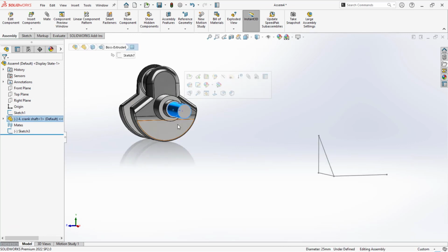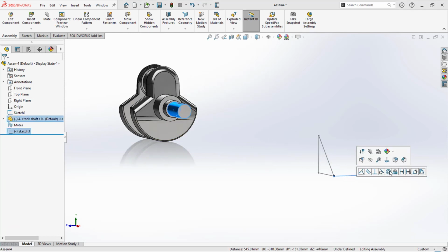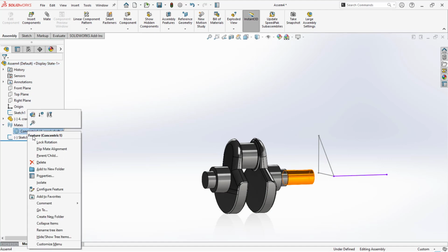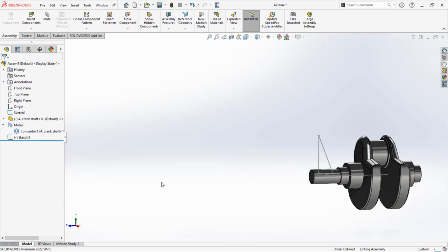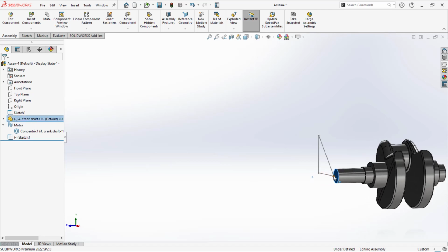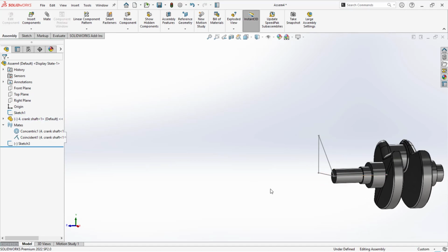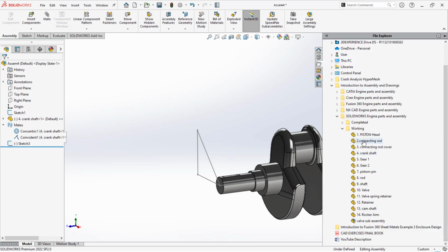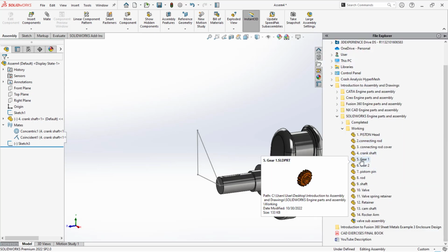So this circular face and this one concentric, I need to flip this. The alignment is something different here. So what you can do is use the mates drop down, right click on it instead of going to edit and making the changes. Just use this flip alignment. These two faces coincident will place it at that particular location. It has the rotational DOF, degrees of freedom.